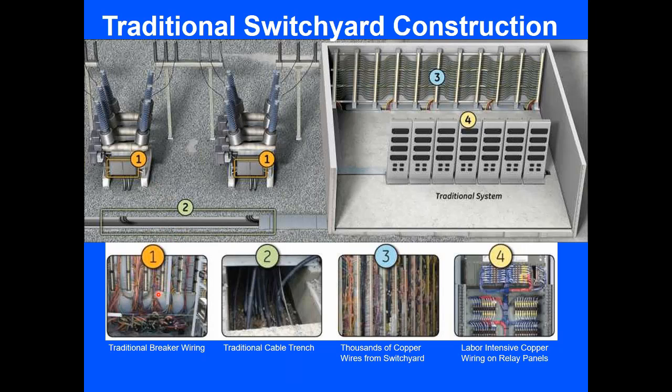So you've got this mass of terminals where I bring all those CTs, PTs, and IO connections. Then they had to run it through a trench and get back to all these connections, typically set up on a wall in the switchyard, and then connect them to the relay.